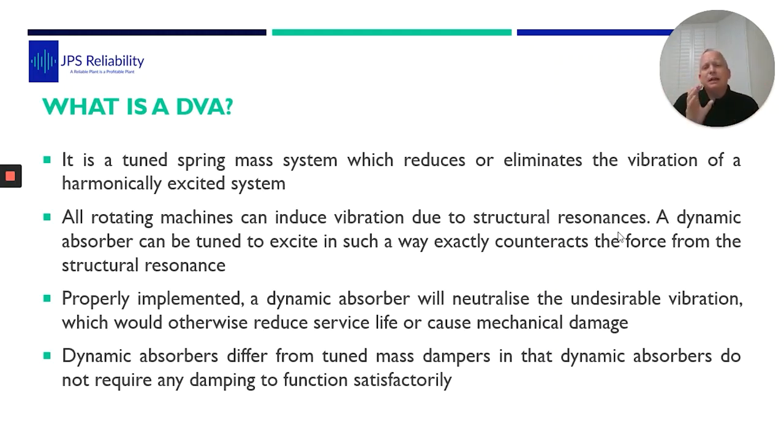They're different than tuned mass dampers. So you think of the Tokyo Tower with a huge ball when the earthquake comes, that's like a tuned mass damper. We're doing a dynamic vibration absorber. You might know these from some suspension bridges. When the cables come down, they've got these little wire things. So when the wind hits a certain speed, these will vibrate. And all the power line overhead cables are going to be resonant at a certain frequency with wind aeolian flutter, but they will have those little dynamic absorbers. And I even think some old cars in the States had exhaust problems, rattling under cars. They have a dynamic vibration absorber to solve it.